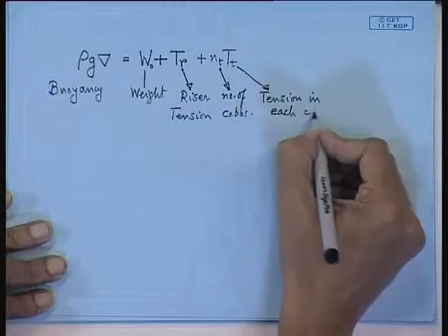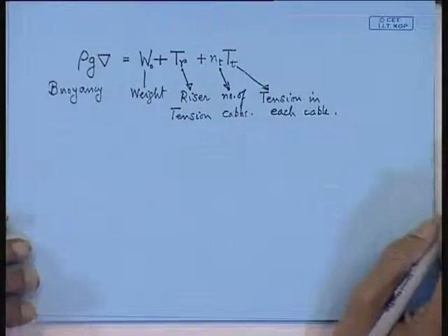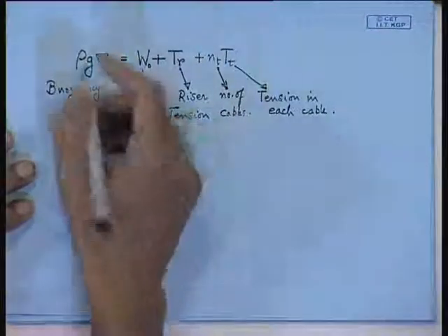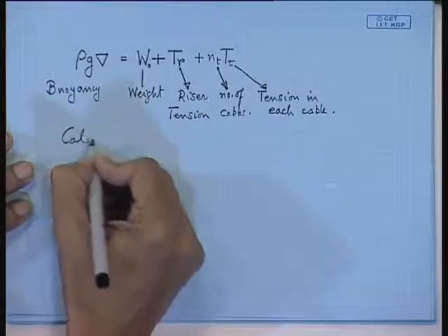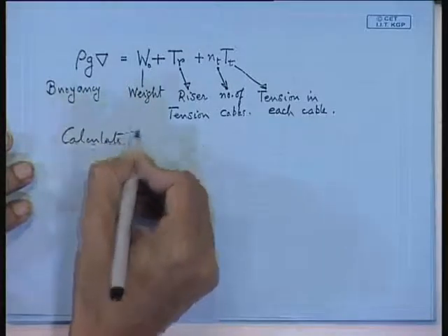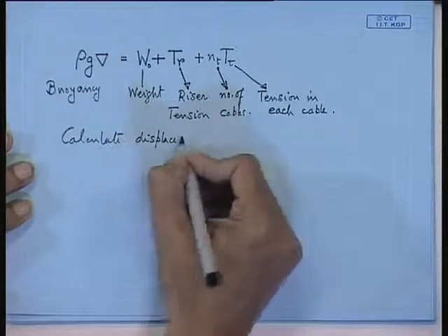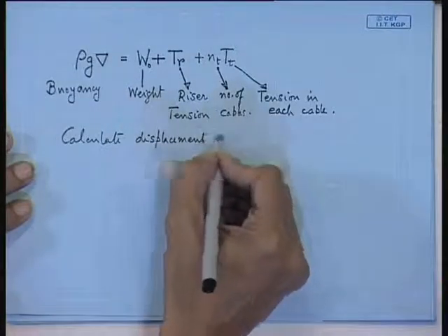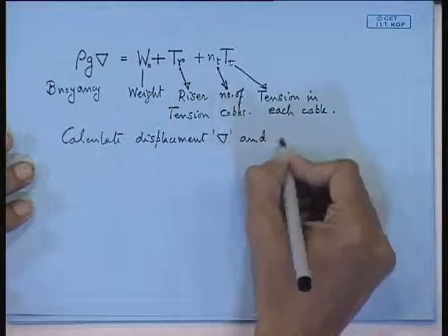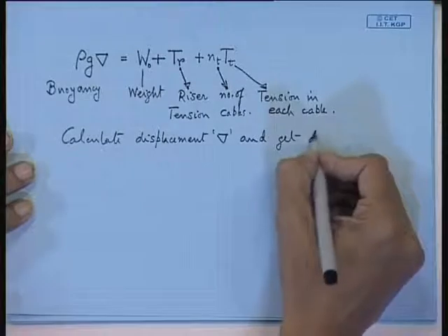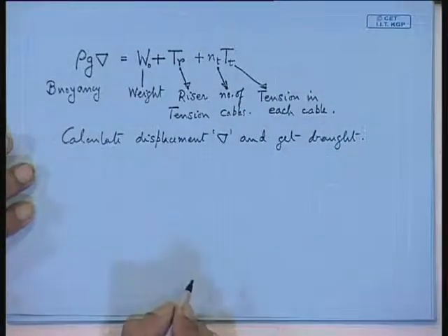So, this is your basic equation, the hydrostatic equation you have to formulate. From this you calculate displacement and get draft. So, this is a hydrostatic equation.